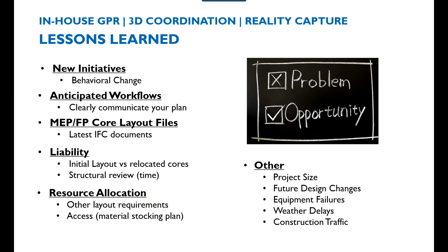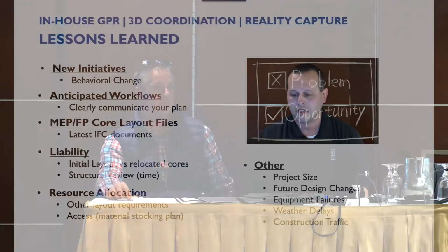Weather delays. I had never even thought about this one, but guess what? When it rains, the slab absorbs all the moisture. You can't just squeegee it and come back the next day. That moisture is embedded in the slab, so your GPR scans are now distorted. But how do you control that? So again, just talking about it up front, making sure everybody understands the time of year.